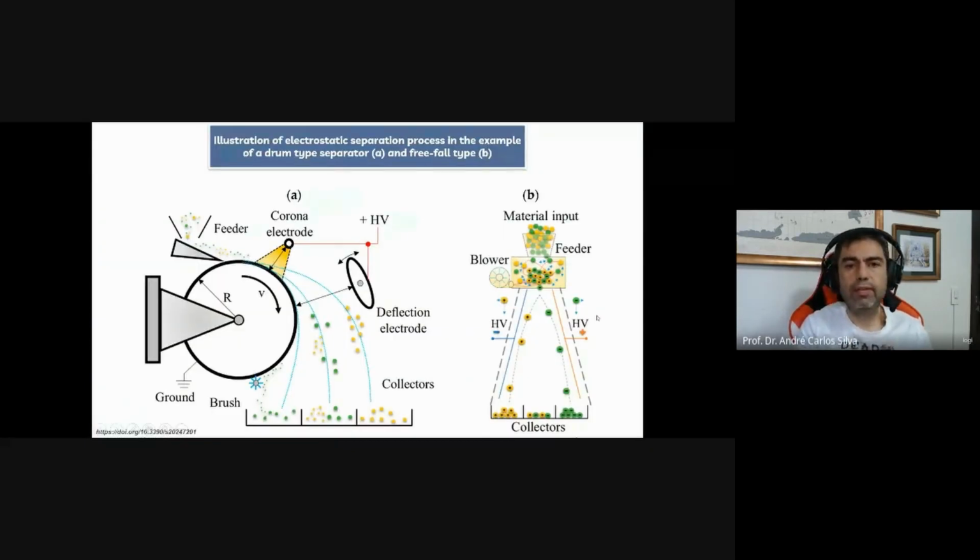Those are the main things that we have to consider. So in this case, we don't want water, we don't want it at all. If you live in an area that has a lot of water or rainwater, then you shouldn't consider using this kind of equipment, because you're going to spend a lot of money, not only to produce the electrostatic charge in your material, but also to dry your material, okay? And that's why you should consider moving away from this technique.